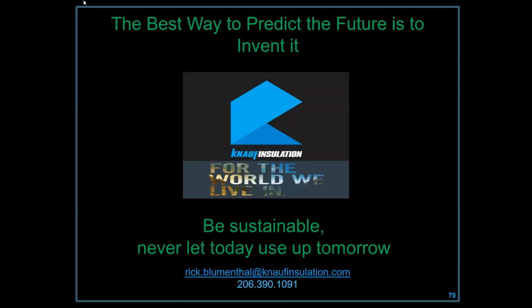His fingers would determine what that gap was. Today we talk about a 2-inch gap between the back of a mortar, brick, block, rubble, whatever, behind that for your drain plane. And then the wall system behind that gets treated just as any other framed wall system would, or even if it's a block wall system, you still have to have weather-resistant barriers, drain planes, etc.